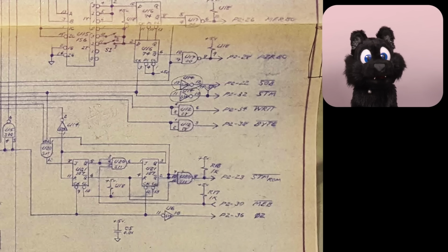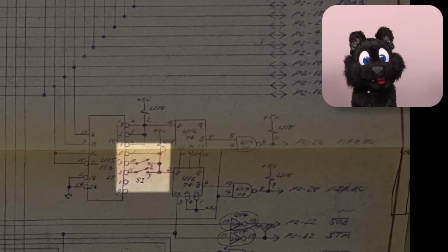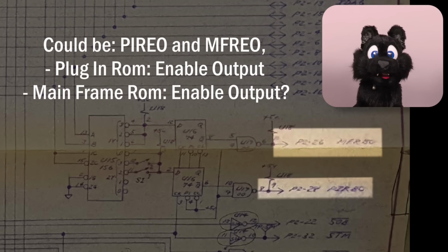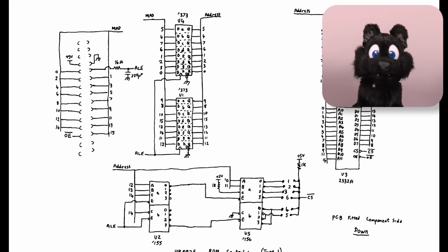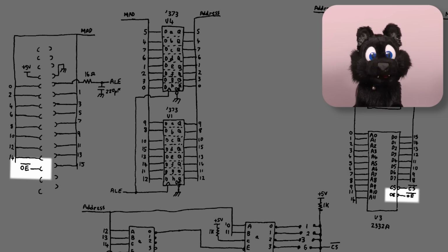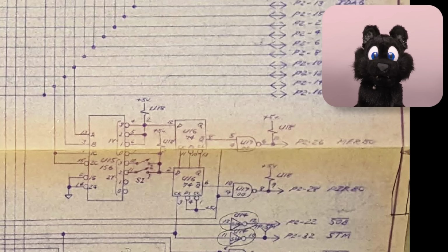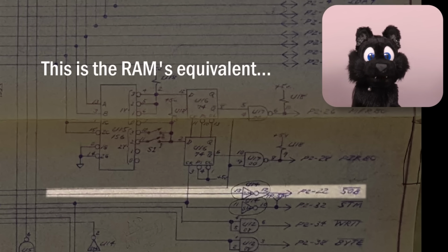Anyhow, the border between the ROM and RAM area can be set with two dip switches on the CPU PCB, and it will only affect the other split signal. I can't fully read the name of either of these, but the signals are there to send the ROM units the final Put Data on the Bus Now signal. This is essentially the output enable signal for the selected memory chips. Overlapping RAM and ROM regions might clash for that reason, since RAM doesn't care about that switch.